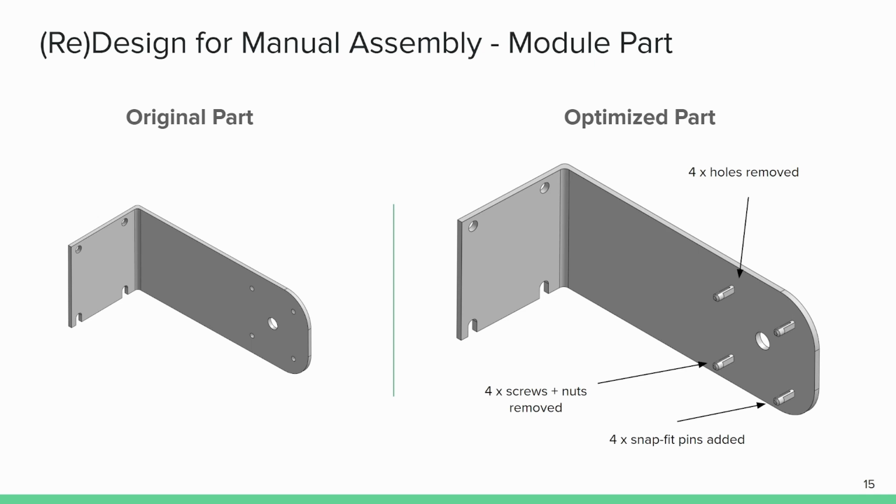The module part that we decided to optimize, the two steps identified two slides prior, is the mount. This redesign eliminates 4 fasteners and is focused on the mount, our module part. This is a functionally important part as identified in the quad chart since it provides stability to the full assembly. The DFA redesign on it is meant to optimize the duration of time that it takes to install the part.